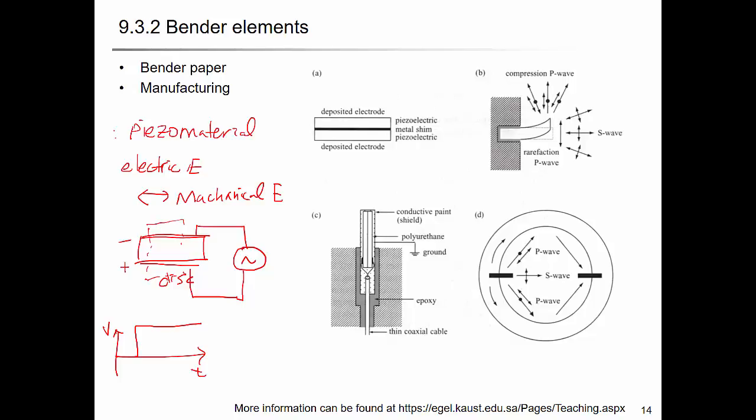Actually, it could be different modes. So there are many modes depending on the type of the piezo crystal, and I'm just showing you the thickness mode here, so that the thickness of the material becomes larger, and because of this electrical voltage, it deforms, and because of the Poisson's effect, you have an increase in height of the disk. Okay? And if you apply the negative voltage, then it's going to expand in this direction. Right? So the thickness will be reduced, so that laterally it's going to expand more.